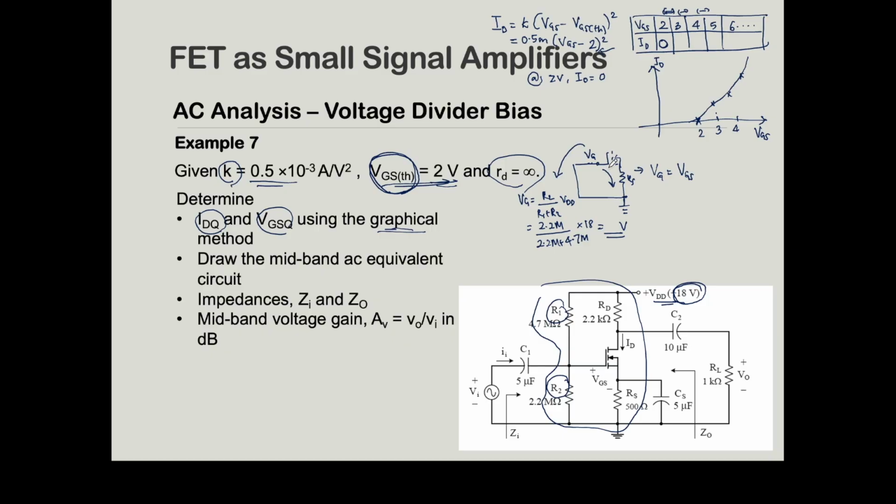Don't forget, we always have the VGS voltage across the gate and source terminal. The current flowing through the RS resistor is IS, so IS is equal to ID. So here we're going to have ID times RS. VG is from the value that you got just now.